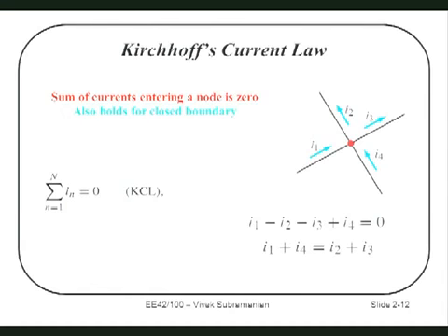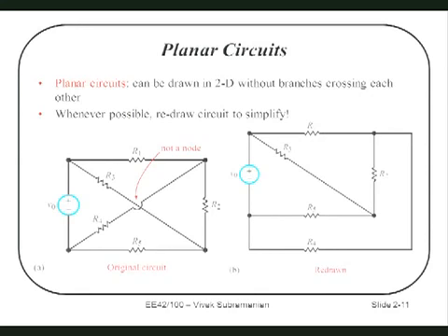currents coming out. This law is a very important law, and it allows us to start doing analysis because we can take a system with ordinary nodes or extraordinary nodes and we can figure out the relative currents. Let's go back to this example. I know that the current coming in through R3 and R2 must equal the current going out of R5 in this case. Let's say current is coming in this way and current is coming in this way. The sum of these 2 currents must equal the current going out of here. So life starts getting easier. I can start simplifying.